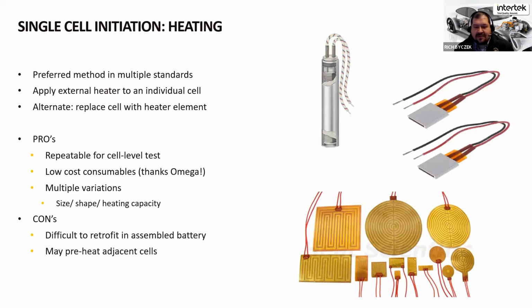So there's a lot of methods here within heating, a lot of ways to get around some of the difficulties of retrofitting or installing these heaters. Some of these thin cell heaters can be somewhat easily installed as part of the manufacturing process of just a test sample. Retrofitting can be difficult depending on how that battery is constructed. It may be difficult to actually go back in, tear the battery apart without causing a secondary issue while you install the heater. So, that's one of the downsides. Depending on your battery design, you may have to try and implement this in the production stage of a single test sample rather than retrofitting a normally produced battery.